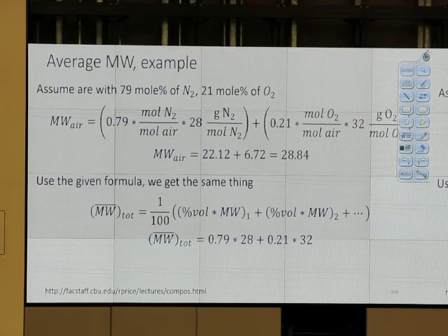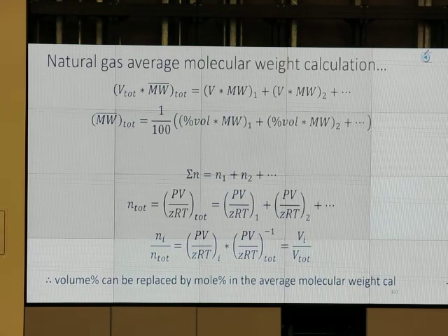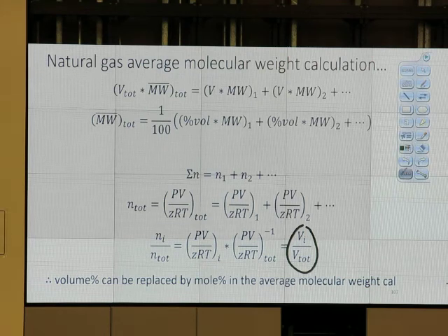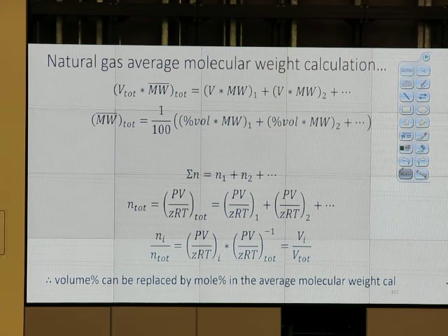Good. And this one is just air. What is the molecular weight of air? I have mole percent. Oh, by the way, mole percent and volume percent, or mole fraction and volume fraction, are the same. Identical. Exactly the same. So you can use one for the other. The reason I say it is the same is based on the derivation. Review it for yourself. But it's just the same. Okay?